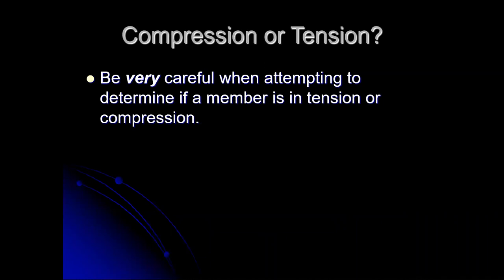But what we're looking at when we do method of joints is not directly the force on the member. We're looking at the force on the joint due to the member, and that causes some confusion. So essentially, we're looking at the loads in a mirror. We have this little thing called Newton's third law that says that when you exert a force on something, you get an equal but opposite force back. And I think the simplest way to explain that and help you see where that confusion is, is a thought experiment.